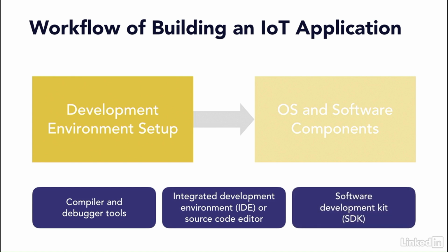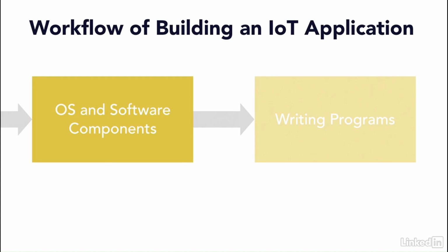You may need an SDK containing the OS kernel with the drivers and the software libraries. Depending on your needs, sometimes the SDK may contain everything you need to start with, but sometimes you'll have to add things manually. These things include software libraries and drivers that are well supported by manufacturers or user communities. If you work on a board without out-of-the-box support from an OS vendor, you'll need to port the OS for a board. If a board has custom hardware modules, the porting is a necessary step to make sure the OS can boot and run on such a custom board.